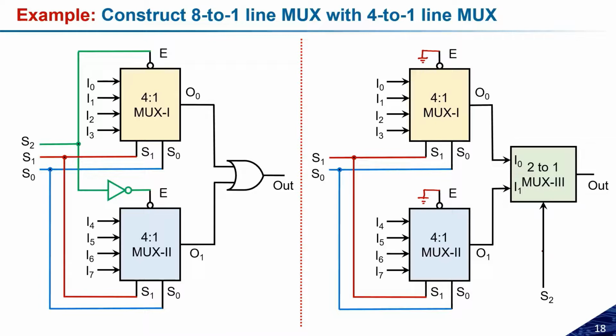Sir, out of these two, which one is more beneficial in terms of time complexity? The first one will be better, because if you look closely, the multiplexer itself is made of logical gates. There may be multiple; if I want to make a 2:1 multiplexer, multiple logical gates are involved. So the delay and area will be more for this 2:1 mux as compared to the single OR gate. So the more optimized one is the first one instead of the second one.